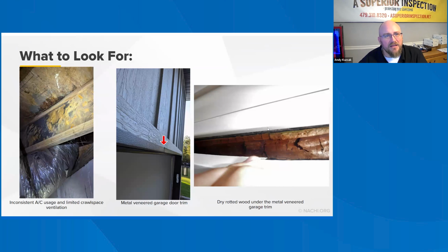And then lastly, these are pictures that I took. So this is the crawl space. There was not enough crawl space ventilation. So the cold duct was creating condensation because of the lack of airflow in here, and it was soaking into the I-joist and into the subfloor. And this was a $1 million home, and this was happening at nearly every floor register. I think we were at like 3,500, 4,000 square feet. So we had probably 20 floor registers that this was occurring at.